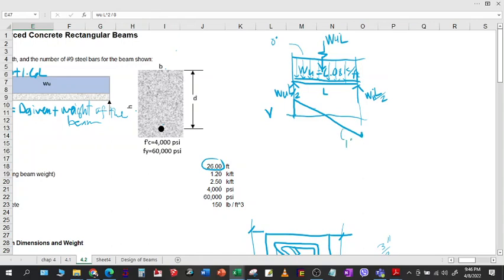And then when it reaches here, this one will be deducted by the area of this load diagram. And what is the area of the load diagram? Area of the load diagram is W, which is the height of this load, times L. So WUL. That is the area of this load diagram. So therefore, WUL over 2 minus the area, which is WUL, that will be equal to negative WUL over 2. So hence this location here. And then it goes up by a value of WUL over 2 also because of this reaction. So it becomes 0 here. And this is now your shear diagram.